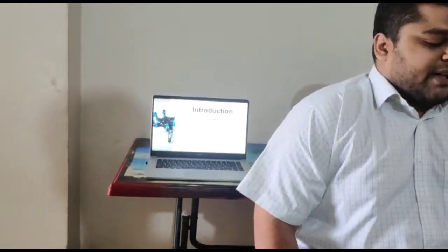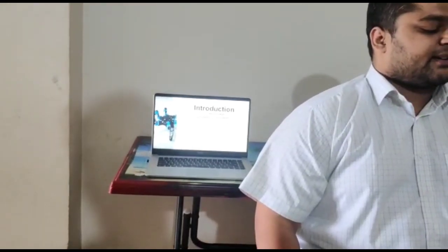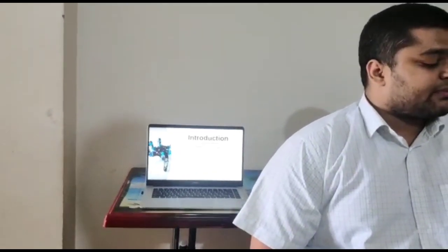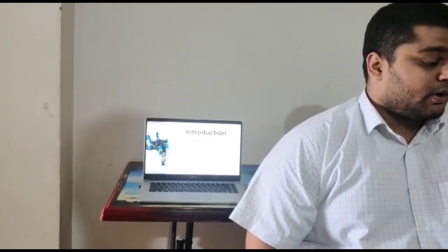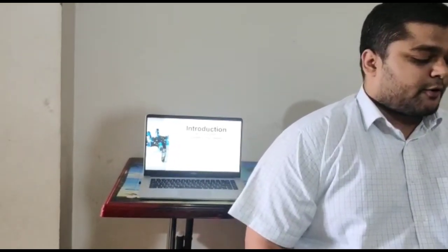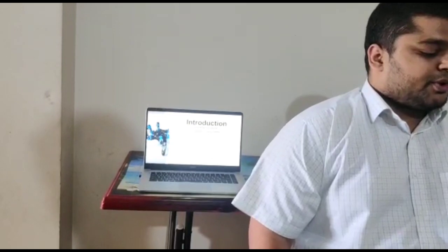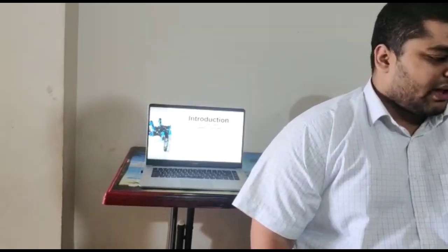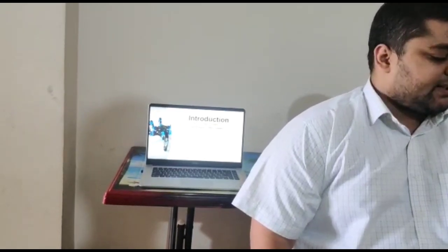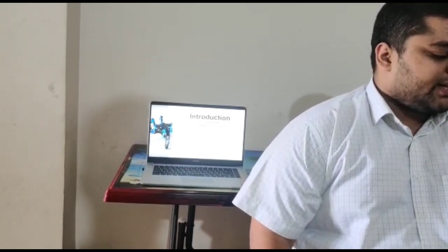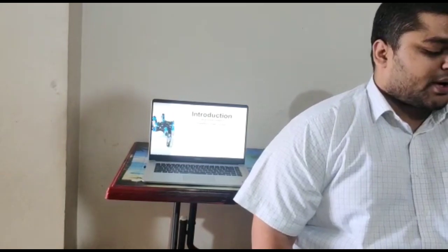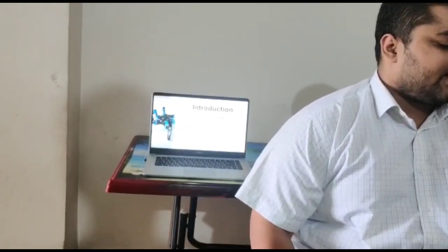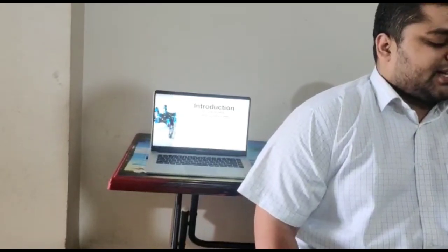Well, from the above definition, we can describe a hexapod as a programmable mobile platform or machine on which six leg mechanisms are attached to the robot body and controlled with a degree of autonomy that allows the robot to move within its environment to perform intended tasks. Hexapods have drawn attention in the last few decades, but only in the recent past have efficient working machines been conceived, designed and built with performance suitable for practical applications.